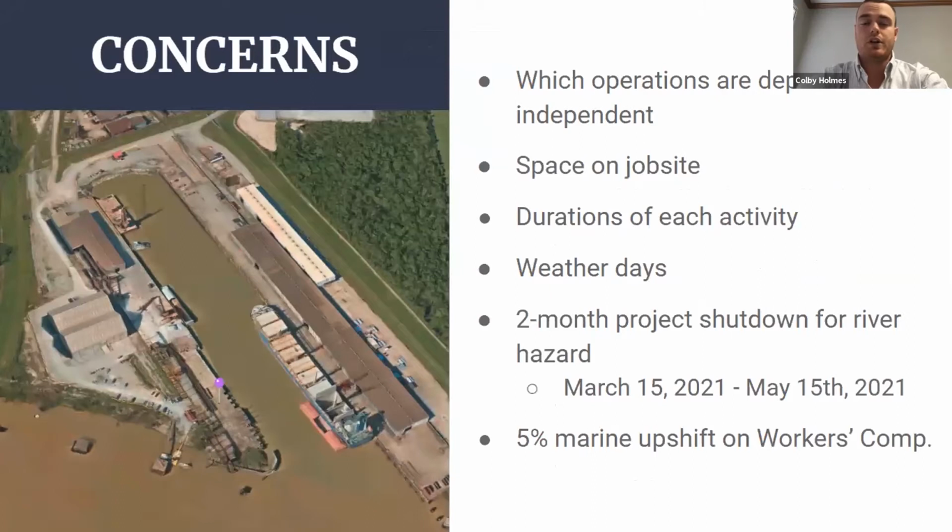During the course of this project, we have a lot of concerns that we want to make sure we take care of, to make sure that the construction process goes smoothly. One concern is making sure that we have our activities lined up in a way that we can be the most efficient possible. As I was mentioning earlier, we'll be driving the steel piles at the same time we're driving the timber piles. We want to make sure we can do this and make things efficient because we're paying for the equipment rental and we're paying for this labor no matter what. So we want to make sure they get as much done as possible and there's no downtime.